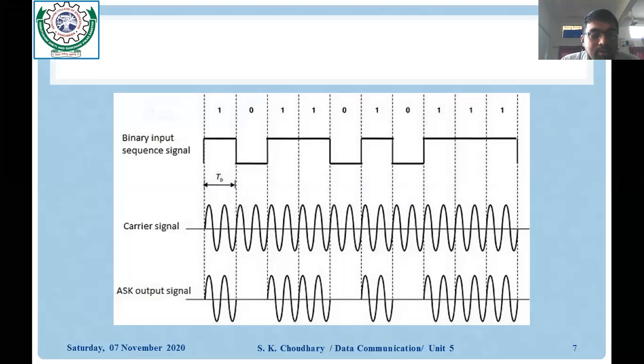You can see the first binary NRZ unipolar signals are there. That's why we have learned line coding, because in this particular unit we would use this line coding technique, the type of representation of the signals. Okay. That's why it is very important. That was a very important topic. So here we are using the NRZ unipolar digital signal, with the pattern 1 0 1 1 0 1 0, like this.